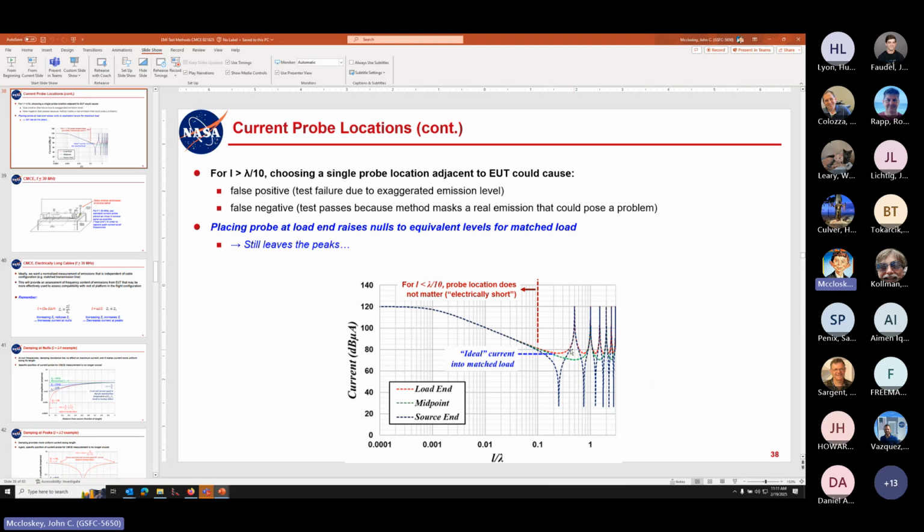But if you're getting some of this type of behavior where you're not meeting the limit at high frequencies, you can get out the absorbing clamp and take some additional measurements for comparison data. But just be careful if you're using the absorbing clamp, and do a bit of homework to understand what you're seeing with it. I hope all that helps.